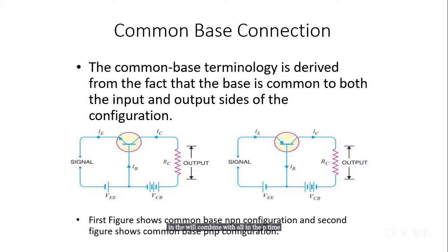However, in fabrication, it's ensured that the base is lightly doped so that the charge carriers from the emitter coming to the collector through the base are not absorbed by the holes.